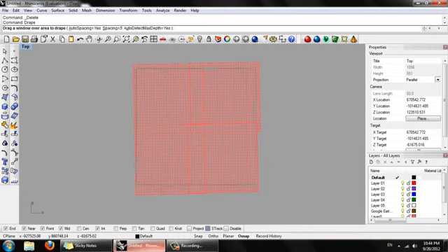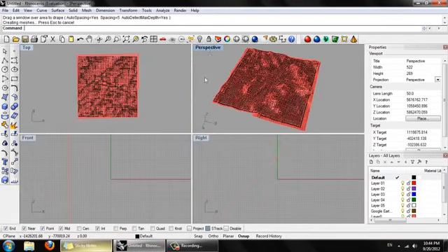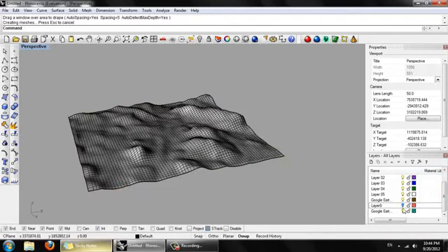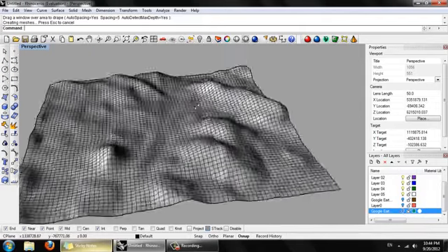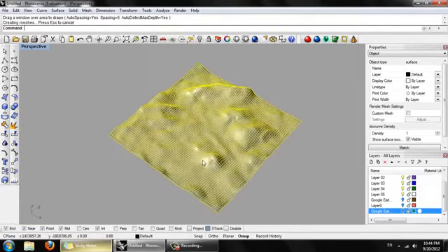Just drag a window that falls completely inside of the boundaries of the 4 quadrants. If we go back to perspective viewport, you can turn off this layer from Google Earth. And now we have a single clean NURBS surface that represents our geometry.